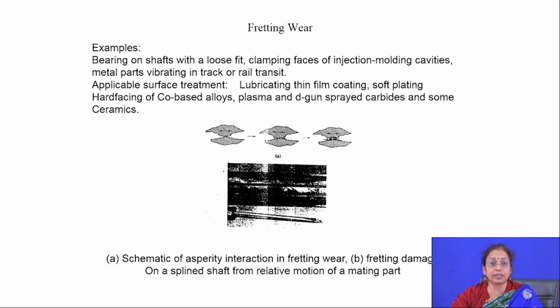the erosion wear process, actually to minimize the failure due to erosion, you basically apply a thin or thick hard face layer on the surface, for which you have to choose the proper material, and usually ceramic materials are used as the material for coating or hard facing in order to reduce the probability of failure of the materials by erosion.